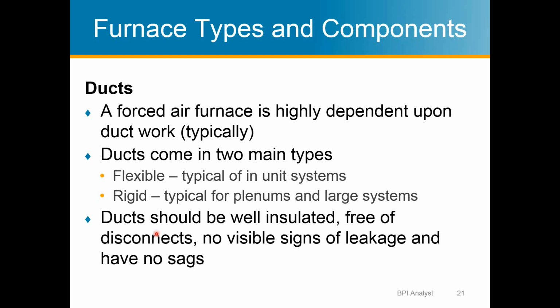So really, this is one of those where homeowners want to change out, want a super efficient furnace, but they don't want to even look at the duct work. They're really hurting themselves because you can't just buy a high efficient furnace and assume you're getting high efficiency into the house. Now, if you're putting that on duct systems that were leaking 30%, and you replace a 75%, right? But ducts are a much cheaper way to make your home energy efficient than changing out the furnace or the air conditioner.